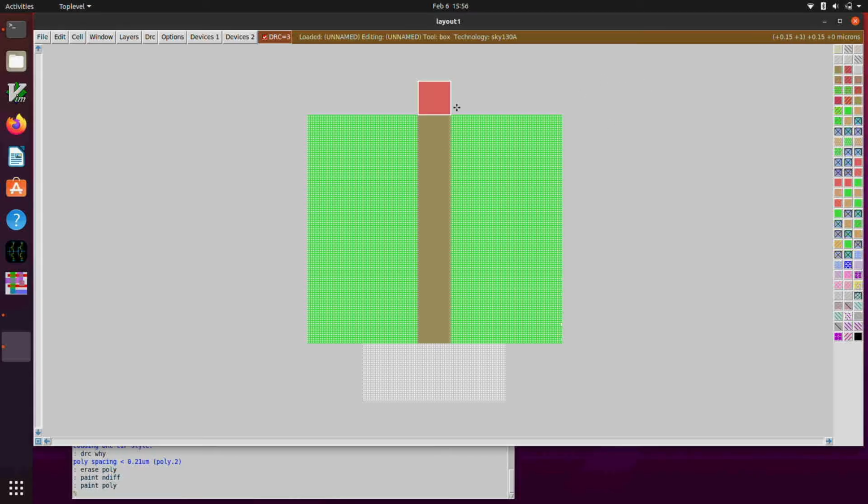And you can see that these design rule violations up here went away. I can do that down here as well. But you can also see that I have a bunch of design rule violations in this whole area. And so if I ask it why it's upset, it says N diffusion distance to P tap, which is a P substrate contact, must be less than 15 microns.